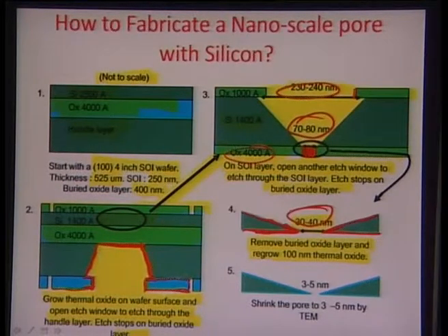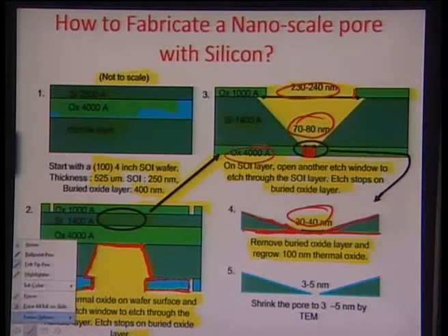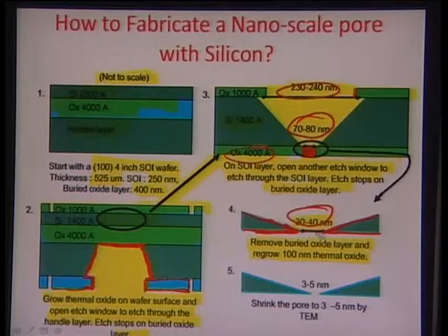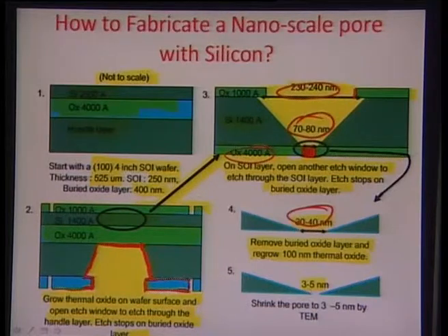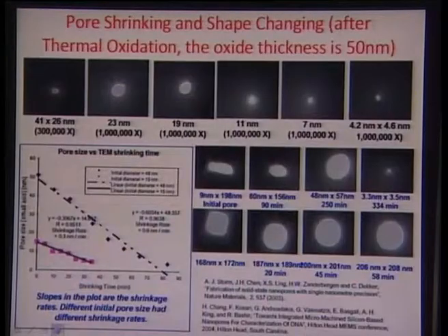Okay. One interesting point to be noted is that if you heat this region using a focused beam, let us say you are using an e-beam, an electron beam, to heat this particular area, you see that this oxide reflows and tries to have a self closing gap. So, this 30 to 40 nanometers can be reduced to about 3 to 5 nanometers, as you can see here. Okay. So, you are regrowing the oxide and you are trying to flow it so that it becomes self closing. This is illustrated here in the example.